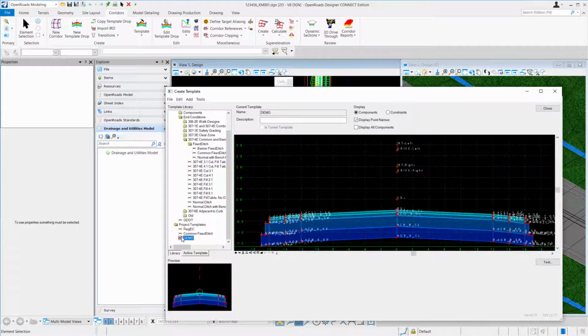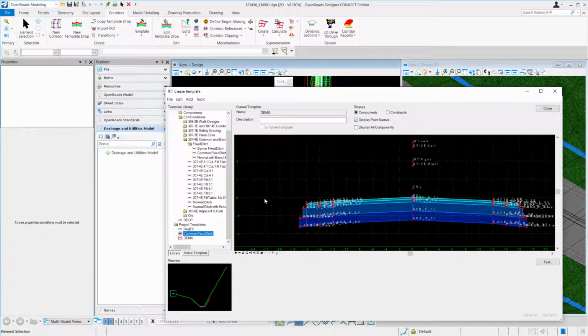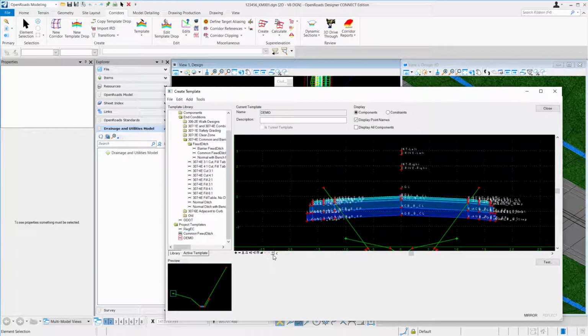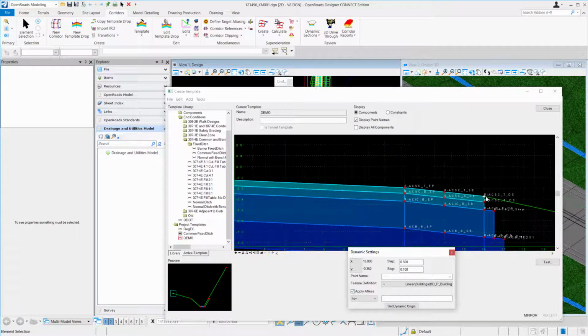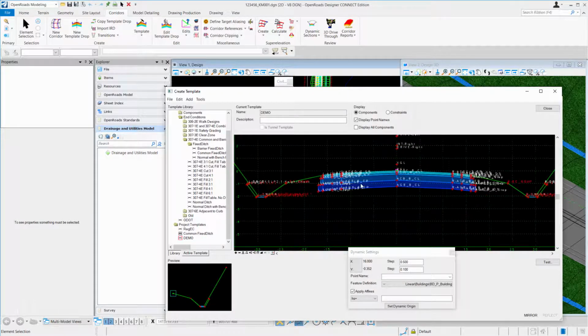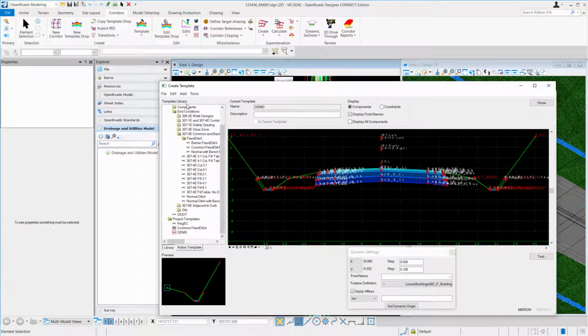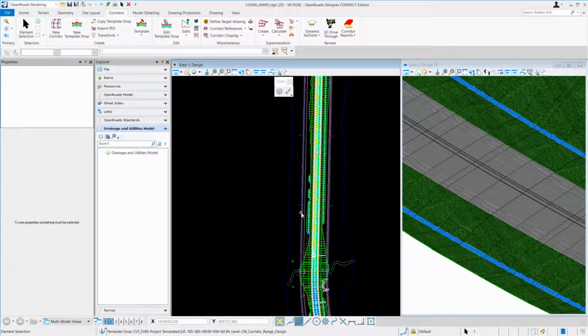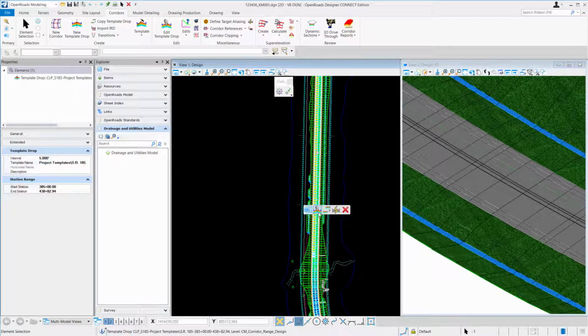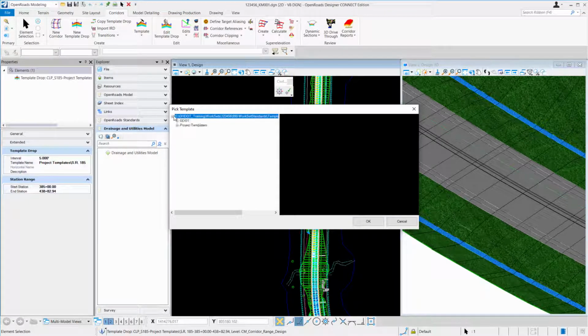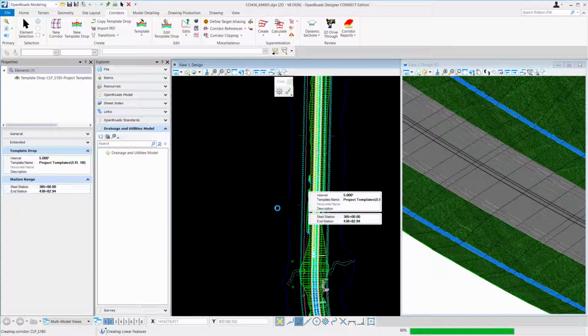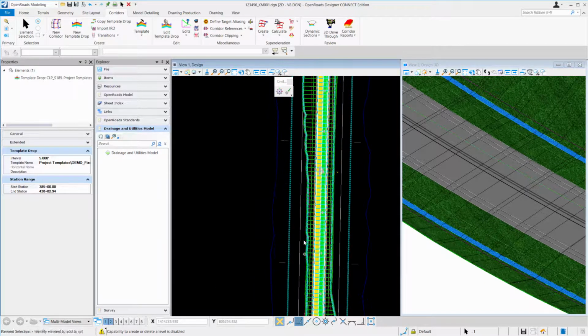So let's go to our demo. Let's add this fixed ditch in first. I'm going to mirror it. I should make sure my apply fixes are on. I'm going to snap right on there. Okay, now I've got my template ready to go. Maybe I'll rename this to fixed ditch. Let me save it, and let me switch this template out. Pick this one. Okay, so now you can see that I've forced a ditch through this whole thing.